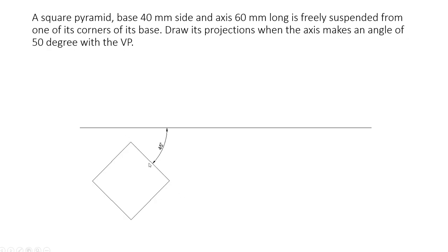On that 45 degrees line mark 40 mm, and make the 40 mm square in such a way that one edge is at 45 degrees. Mark a point there, then mark 40 mm, then a perpendicular line of 40 mm, and in that way draw a square. So one base edge should be inclined at 45 degrees.